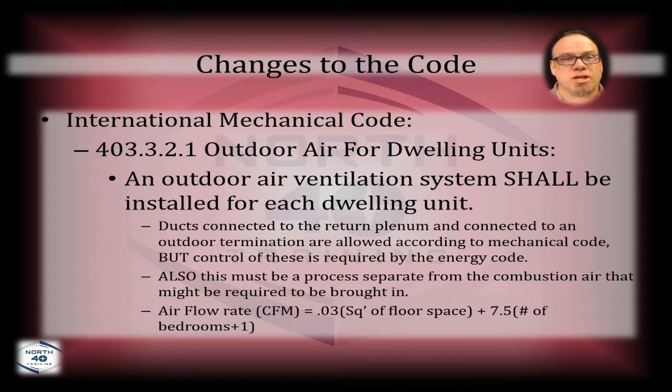Well, how about for combustion air? Combustion air usually isn't an issue unless you look at other codes other than just the International Mechanical Code. There are some codes out there that tell you if you've got two appliances, the exhaust from one appliance can't be any closer than 10 feet from the intake of the other appliance, which would be your combustion air draw.